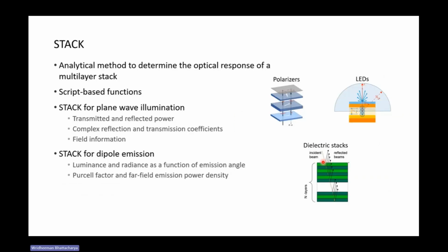So after FDTD, there is another solver, namely STACK. STACK is basically an analytical method to determine the optical response of a multi-layer stack. It is mainly a script-based function because it is quite difficult to alter the different layers manually, right?